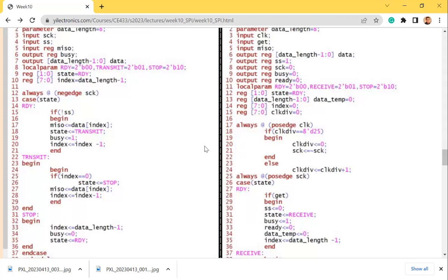Because this guy is not intelligent, it doesn't have a CPU on it. It's just the SPI module, like I just said. This is the photodiode sending a photocurrent to this little chip on the module. The chip converts that photocurrent into voltage and digitizes it using the ADC. All these bytes are sent to the SPI module and sent out from the serial port, which is SPI.